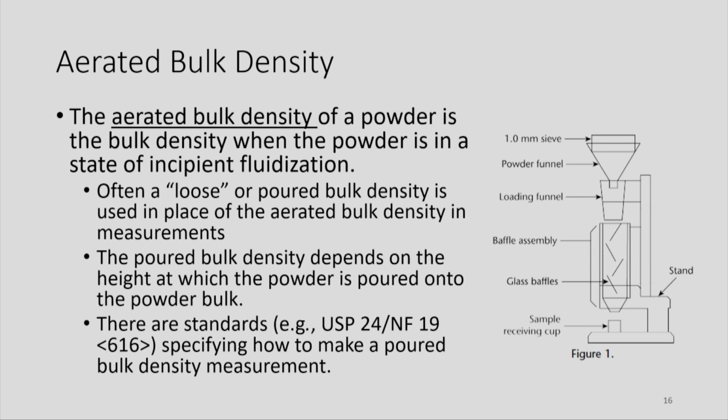Okay, so again it's common. How many of you measured bulk density in the lab? Most of you, right? So you make it flow through a funnel, and then it falls into a container and you get the weight, right? So that's common. For grains and larger materials, we will not use this kind of baffle assembly, but it's most commonly used for small fine powders.